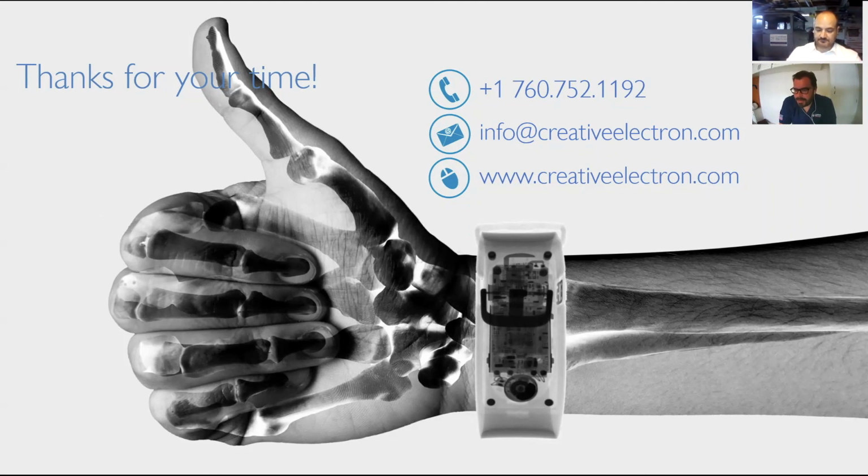I do have some experience in PCB design. Passive components are usually filters and things like that. They can be moved, by all means, taking the design into account. Moving one to the opposite side of the board doesn't make sense because you're adding traces and making it more complex.